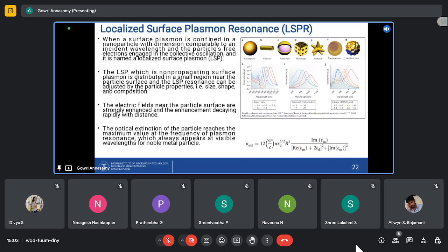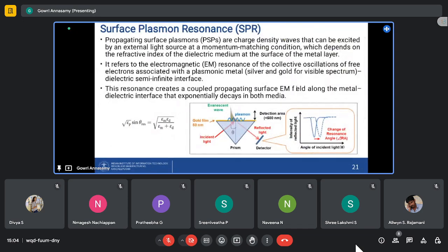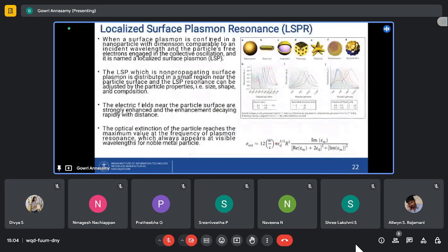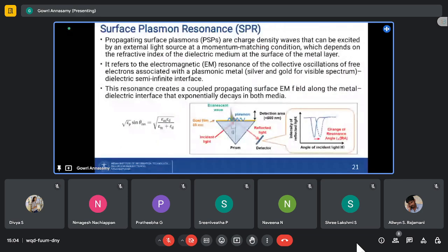Evanescent wave absorbance biosensors are intensity modulating sensors where we are interested in measuring the changes in the intensity. FBG, fiber Bragg gratings, are wavelength modulators, where we are interested in measuring the reflected wavelengths by fine tuning the grating interval. And we have discussed interferometry for measuring the changes in the phase. And for the sensitivity enhancement we have looked at SPR, where we are employing a gold film of nanometer thickness, and it's LSPR when they are localized into individual particles and they exhibit absorbance. Here they exhibit changes in the resonance at a particular wavelength of the reflected light.